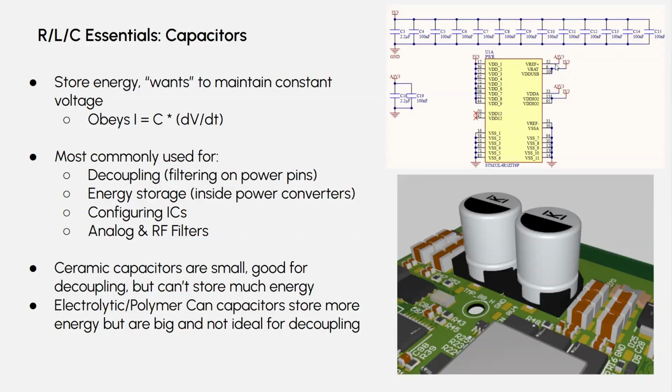So we have these right over here. These A3v3 is like analog 3v3. We sort of separate analog and digital power again for noise reasons, and so this is the same as the capacitor bank on the top, but we've just put it physically different so it can be visually distinct. And yeah, it does look weird because they're not connected. You're like, why not? But they are. It's just you've labeled them right.